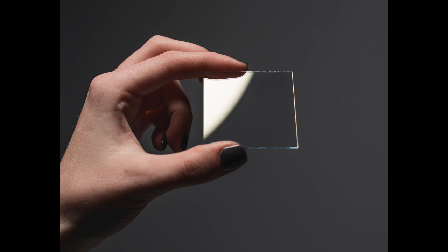Indium tin oxide, or I.T.O., is the most commonly used transparent conductor. It can be up to 90.2% transparent, while maintaining a conductivity of 7.2 × 10⁻⁴ ohms per centimeter. This pairing of conductivity and transparency is extremely rare. The material needs to have a band gap just large enough that visible light can pass through, but narrow enough where it can still be conductive.